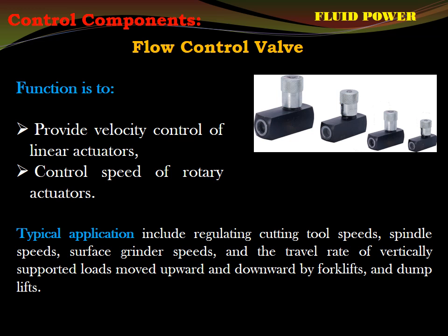So flow control valves, as the name suggests, control the rate of flow of fluid through a hydraulic circuit, and FCVs accurately limit the fluid volume rate from a fixed displacement pump to a branch of the circuit.